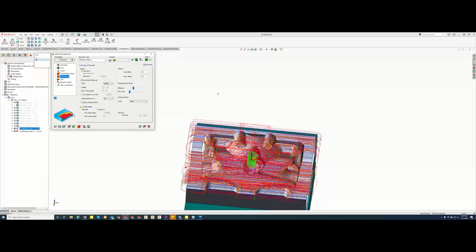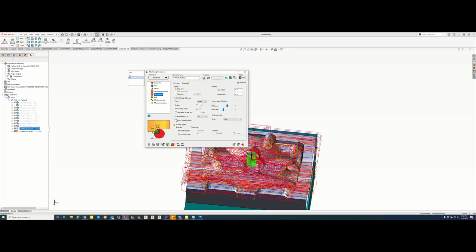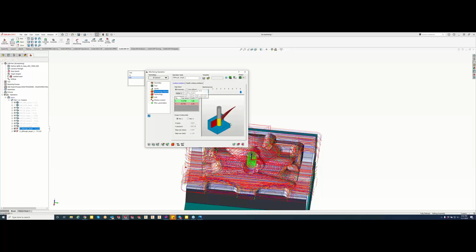Obviously, you're not going to be doing a ton of huge material removals, but where it really comes in handy is protecting those smaller diameter tools. So if you are using some small end mills to do some face milling on a mill turn center, because we are monitoring that angle engagement, you can really protect those tools and get some very high efficiency removal rates using iMachining on mill turn center. And that's using the XY axis, and you can also do it in an XC with iMachining, where you're using the spindle to rotate as the X is modulating.